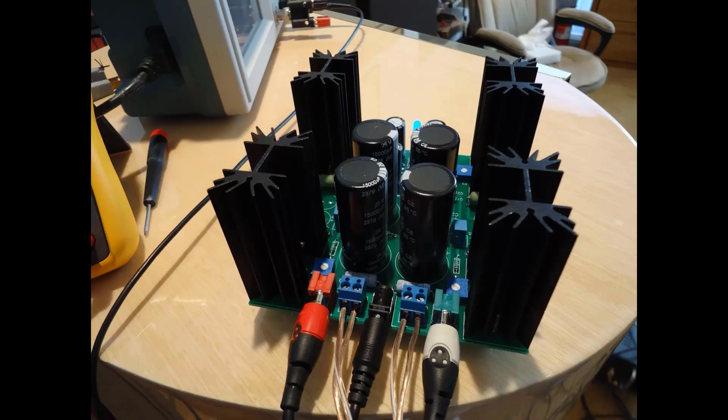Here is a photo of the prototype. The amplifier sits on a single circuit board, roughly 5 by 5 inches, which holds everything but the external desktop switching power supply. You can see the 4 heat sinks for the output transistors and the capacitors for separate supply filters for each channel. Also the output capacitors, plus the connectors for power, inputs, and outputs. The amplifier can be operated as a standalone or it can be mounted in a chassis, which should be well ventilated.